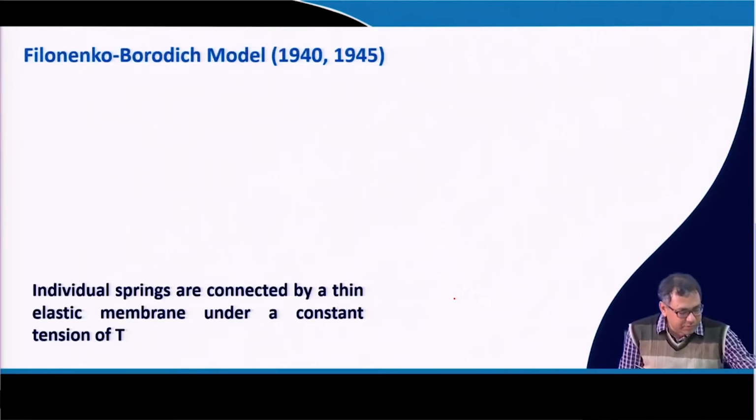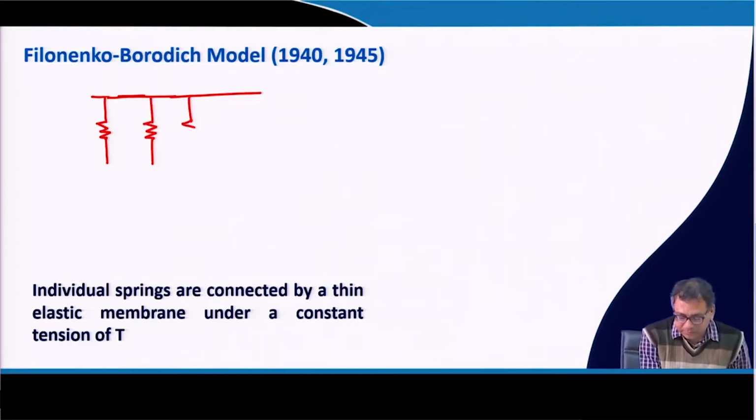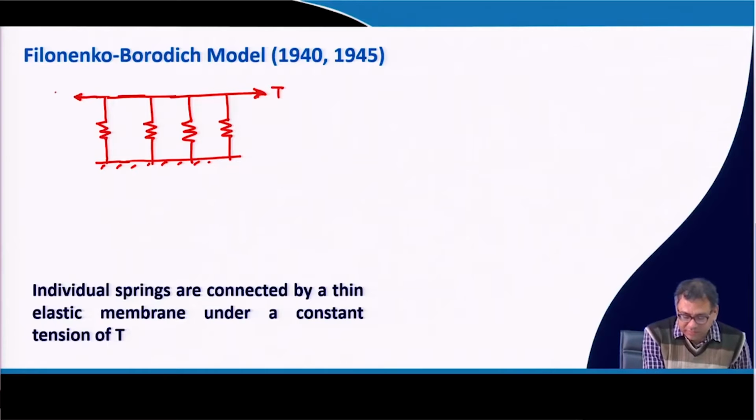So to remove that connectivity issue, Filonenko and Borodich proposed a model where these springs are connected by a stretched membrane. Suppose these are the springs, so these are connected by a stretched membrane. So this tension is equal to T.